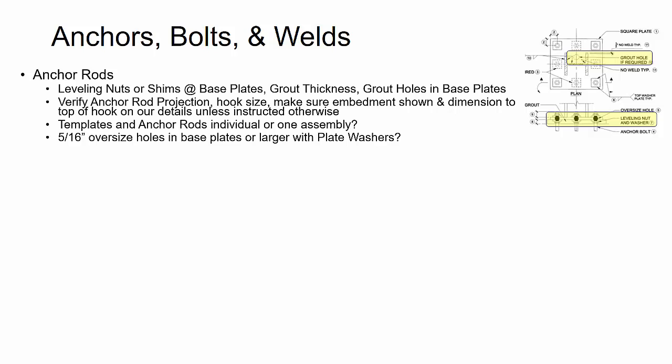Very first thing is on anchor bolts. Are you using leveling nuts or shims underneath the base plates and with the grout? Do you need a grout hole in the base plate to get access for the grout? Looking at the oversized holes, are plate washers going to be required on the base plates? So these are things, and then even the grout thickness if you're using leveling nuts.